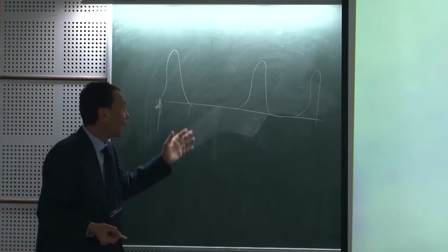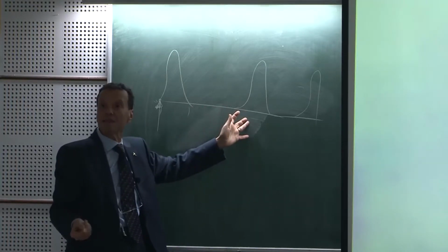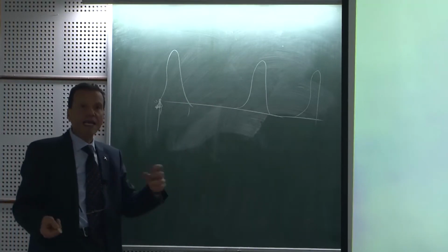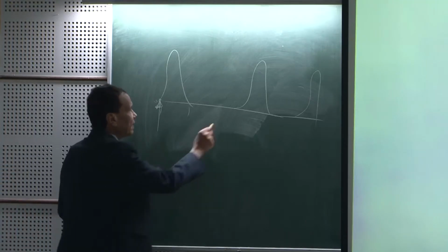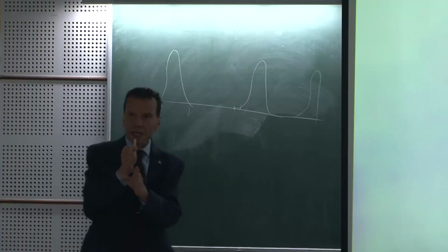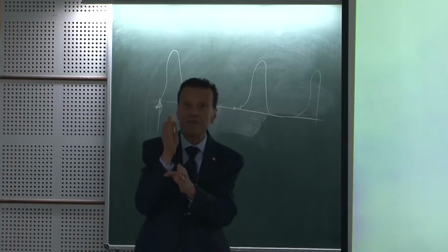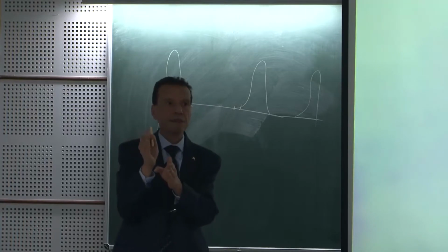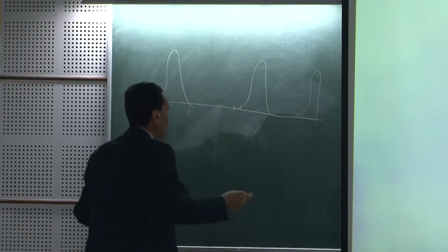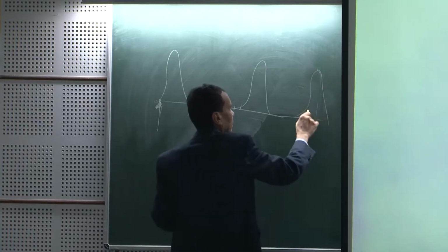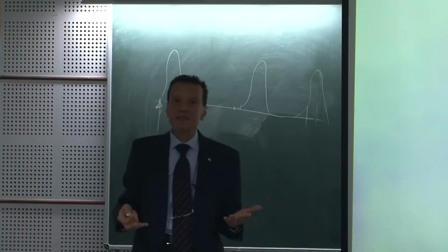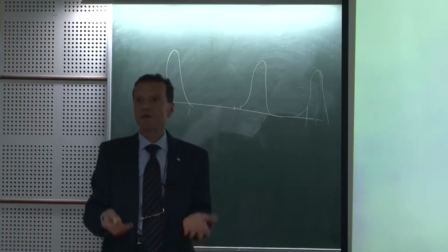I will catch the second sample from the second slice, or from the 100th. Because I'm not fast, I will wait. This is the first sample, I took it here. I take the second sample here by just shifting the firing time point a little bit. And then the third sample is taken from here. So after a number of pulses, you can have enough samples from the same pulse.